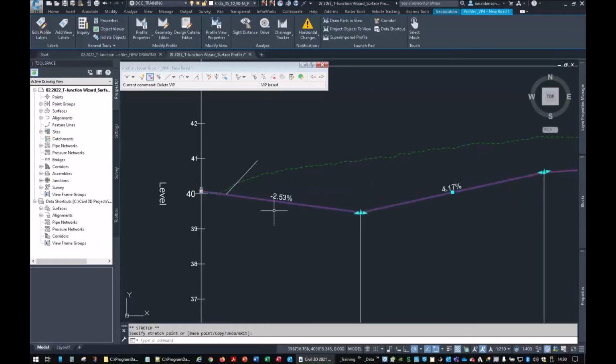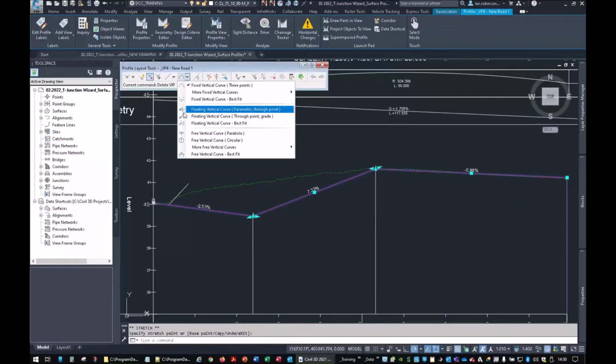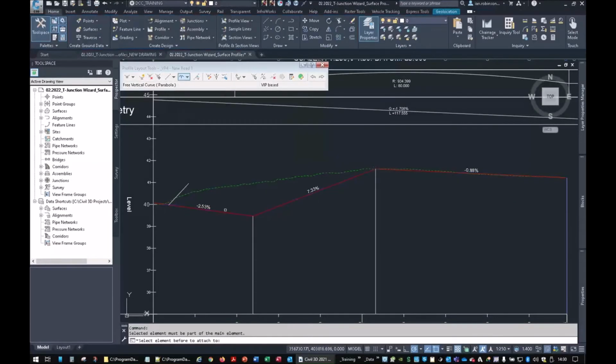I'm going to unlock that point, use the grips to bring it across because I don't want any vertical curve, because of course I'd break my Ferrari balance at this point, wouldn't I? It's a bit too steep. And I reckon it'll let me delete that point if I wanted to, but I don't want to now. But it'll let me move it. There. Okay.